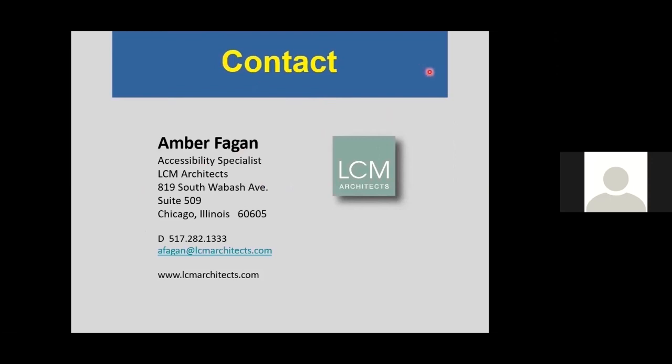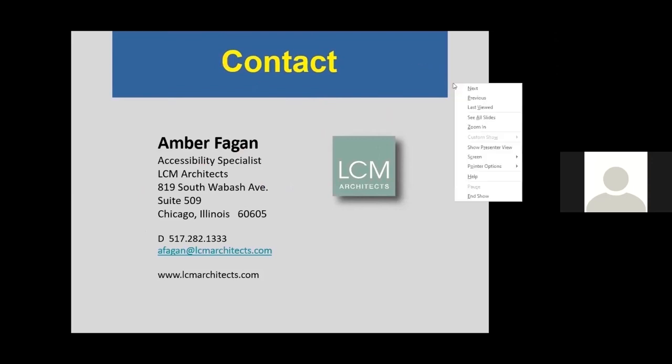Here we go. Okay. Should washing machines and dryers be accessible? In public and common use spaces, at least one of each type of laundry equipment is required to comply fully with the ANSI standards requirements for laundry equipment. In the dwelling units, the short answer is no. A little bit more detail is that now in the ANSI standard, in these dwelling units, you do need a clear floor space in front of the equipment, but there isn't a requirement that the door opening or the operable parts be in reach range.